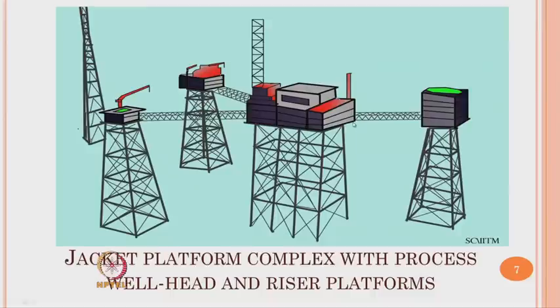They are braced and they also have surface levels of interconnections between the joints, so that the whole system is integrated to alleviate the lateral loads or the wave loads acting on them. And of course, these are the points where this will be connected to the pile and the piles will be driven through the sea floor depending upon the condition of the soil, etc.